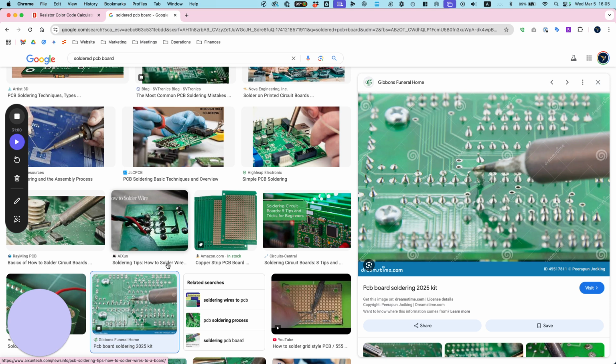How many amps are we using? It's actually really little. So technically we could probably stay here, since this will handle a very low current. But in reality you want to unplug this one and put it into this side. Now this is used for measuring current. So all of these over here need to be using this side. And then for you to measure current, you need to break the system.